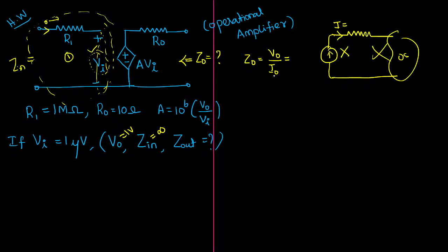So I simply understand one thing. You need not calculate the value of voltage at all. I am simply saying that the input current is approaching 0, so I take the value of input impedance as infinity. But this is not the case when we observe the secondary part. In the primary part, due to this open circuited property, the input impedance was approaching infinity. This is the basic fundamental property of the operational amplifier. So the input impedance offered by the operational amplifier is ideally infinity.